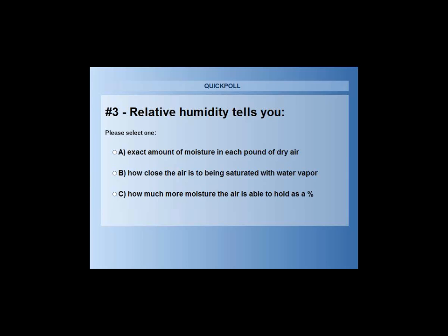While you guys are doing that, I'm going to go back to Peter's question a little bit more, when he asked with slowing the blower speed, what delta T are you aiming for? And I mentioned it wasn't really a delta T target, but just from a general airflow standpoint, historically, systems have been designed to use 400 CFM per ton. Somebody picked that number back in 1950 or whatever. We've been riding that number ever since.